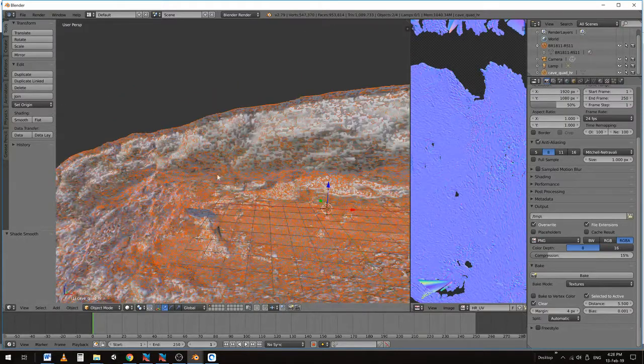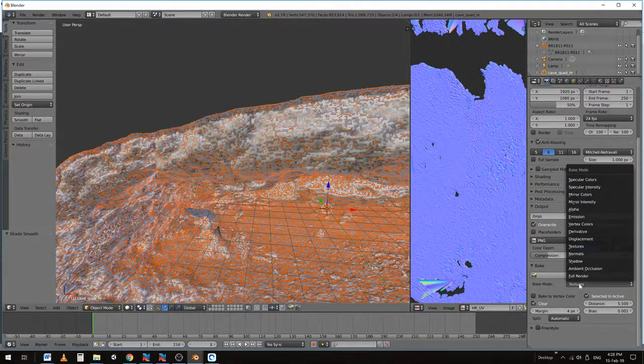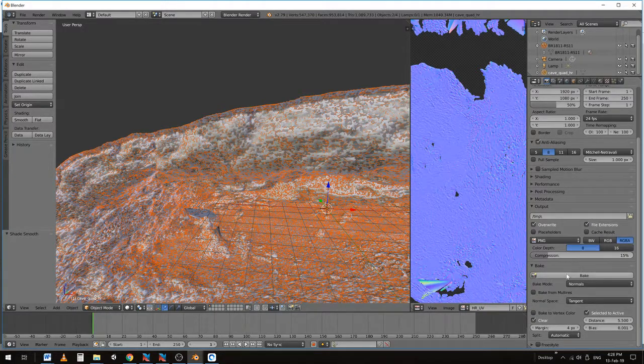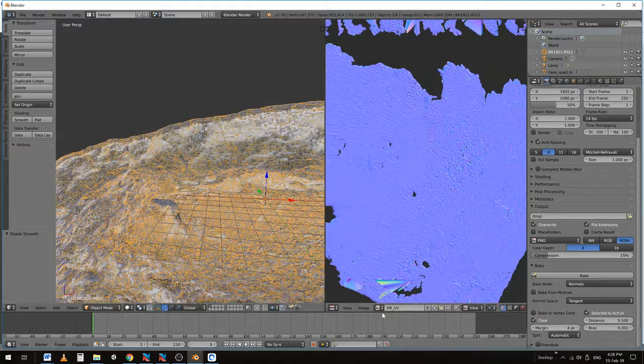So instead of a texture map, we're baking the distances via a normal map. Down here on textures, I click textures and I change instead to a normal map. Now, using exactly the same process that we did with the textures, and in fact, before I do that, I have created a new file, but you can simply overwrite the color file.